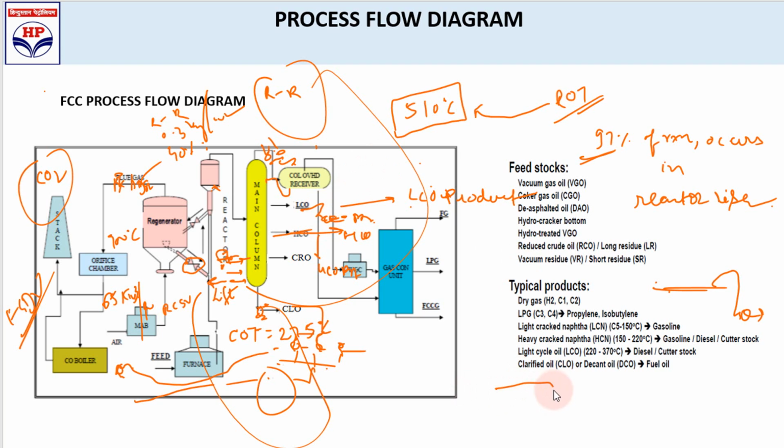The HP receiver is basically a high pressure vessel. From there it goes to the stripper and then to the DB column, the debutanizer column. From the DB column we get LPG and CRN. We send them to FCC and ST for treating, and from there we give the CRN, cracked naphtha, to the MS pool for blending. The LPG we give to Merox for further treatment, then it goes to the bullets for selling.